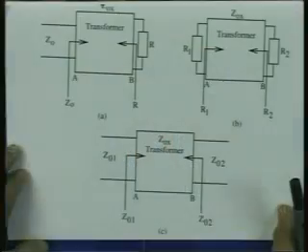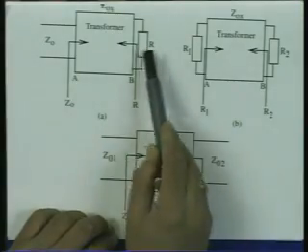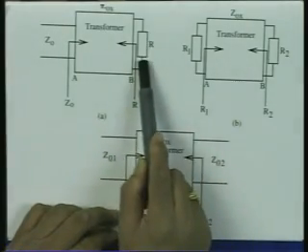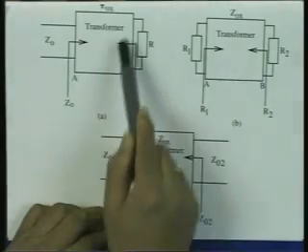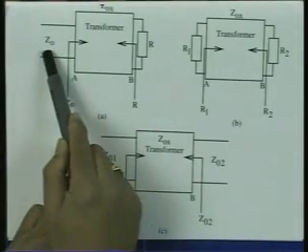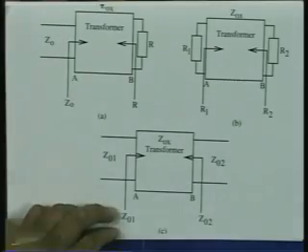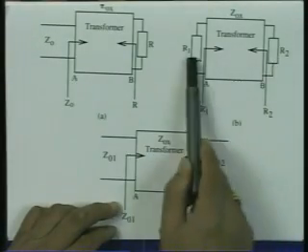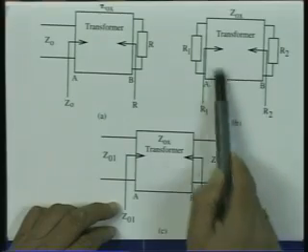What is the application of this? You will find there are many applications where this will be needed. One is a simple case. Suppose I am having a module where the impedance is a resistive impedance. This impedance, when seen through the transforming device, should appear like an impedance equal to the characteristic impedance, one possibility.